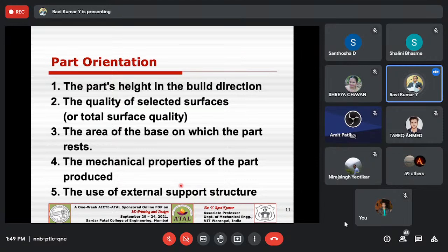If at all it allows introducing two materials, fine, but some of the technologies may be restricted to only a single material, like powder bed systems, right? Where you don't have anything else to add, in that case you use the same material as both model and support material. It's more expensive.